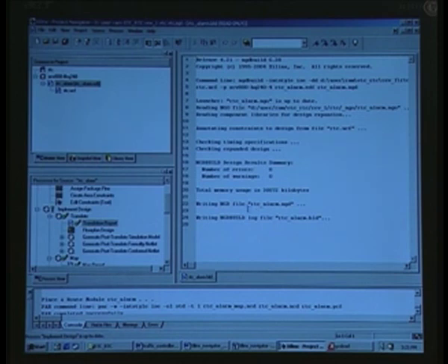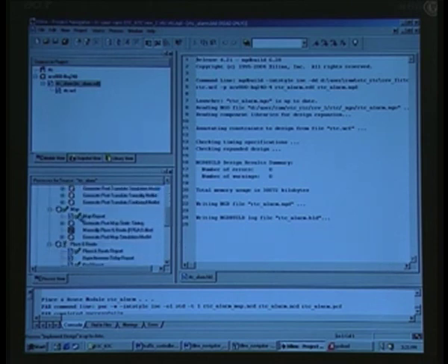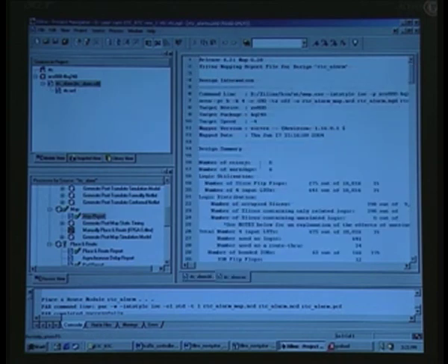This is for the next project that you are going to take up. This is a real time clock. RTC_alarm is the design file, and if you want further details, mapping report, you can just go to map here and then double click on map report, and out comes this. Here we have already read these points, and it reports number of slices.